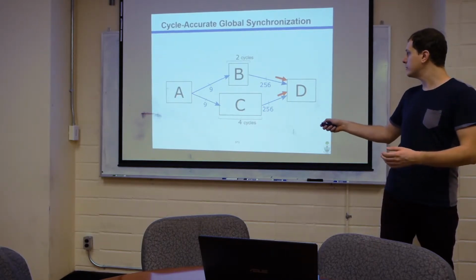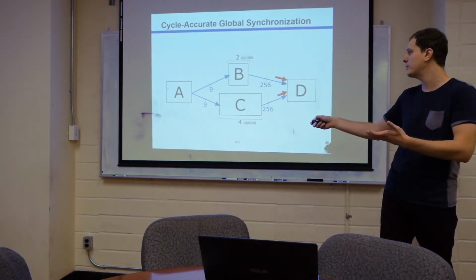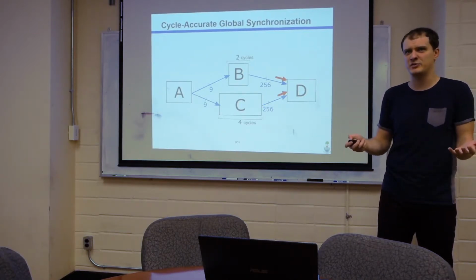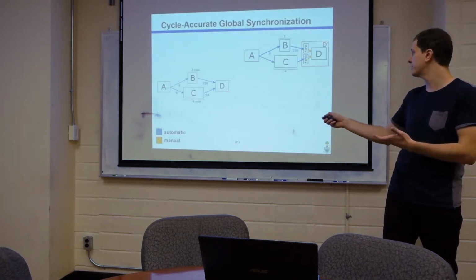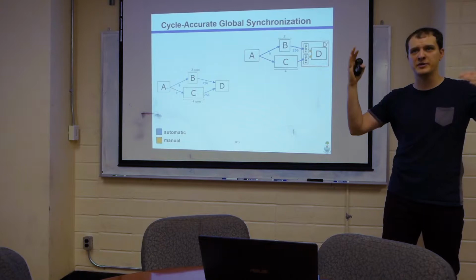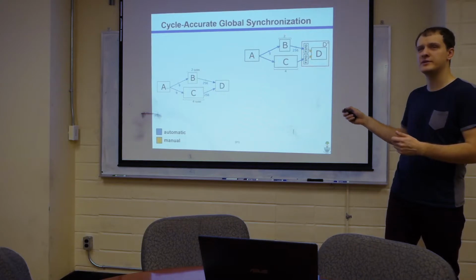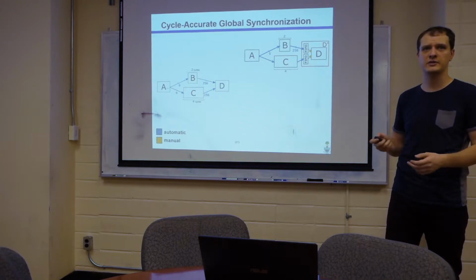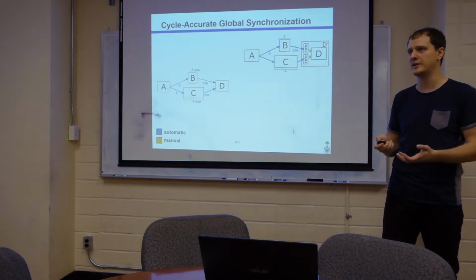Well, if we're building this whole system with an interconnect synthesis tool, we provide the modules, but we don't build the interconnect. We just provide logical links. We don't know about the implementation of what interconnect is going to be along these links. So one easy but not good solution to synchronize is for us to control what we can control, which is the modules. So D becomes D prime, and in it we stick some FIFOs to help us manage the delays. And then we will dequeue together from these FIFOs so we get the synchronization. This will make our design independent of the interconnect design and latency. But it's not ideal because we have these FIFOs here. That's more than what we need to make it happen.